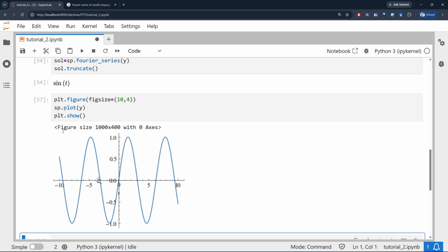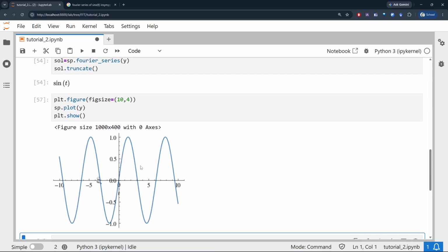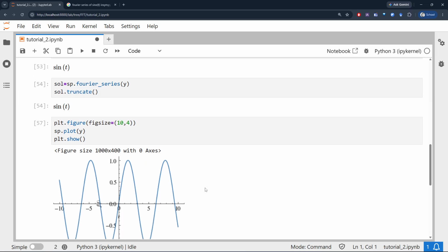Yeah, so you can see that this is the signal. In the frequency domain, it will be the same because it has only one frequency, and we expect the magnitude to just be 1, right? So I want to do that simulation in LTspice and see if what you are getting here is the same as the Fourier transform. For the Fourier transform, it will have only a single spike at 1, right?